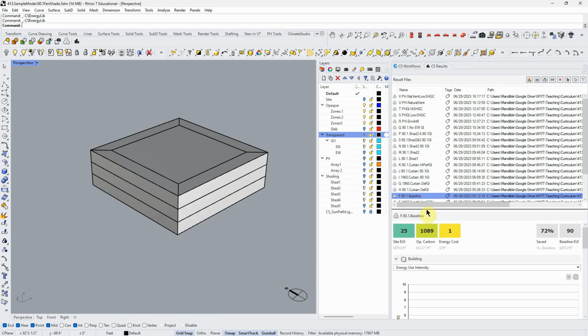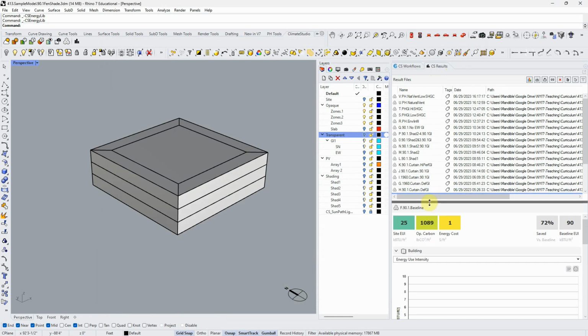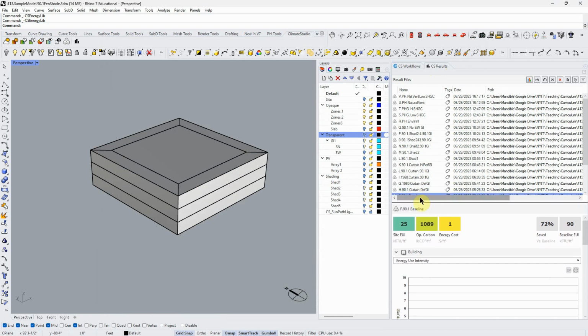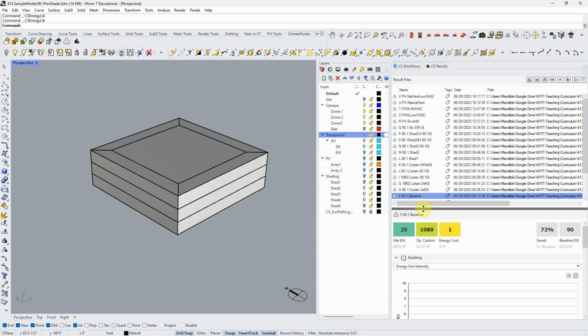And then I started adding glass. I'm just going to click through these, and I can share this model with you guys if you want to see it and mess with it. You just let me know. So the next thing I did was the 90.1 baseline, and I added windows. And you see that, I just used the default glazing, so that's single pane glass, considerable change.